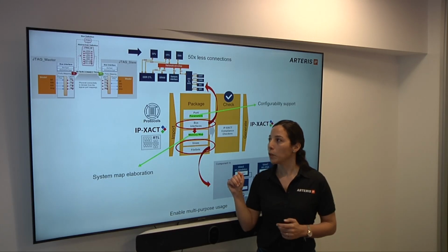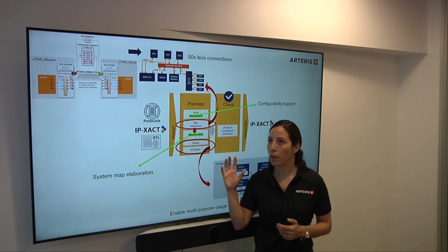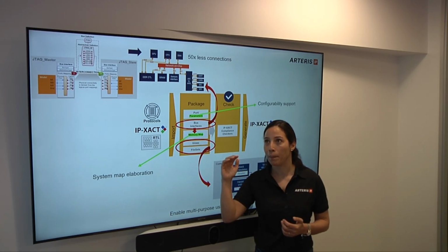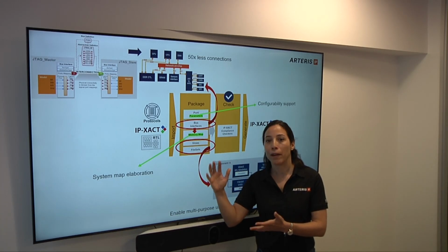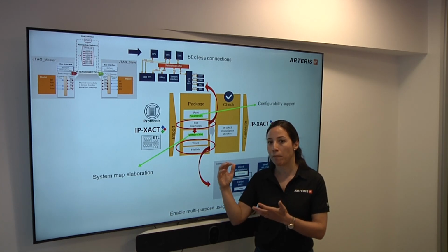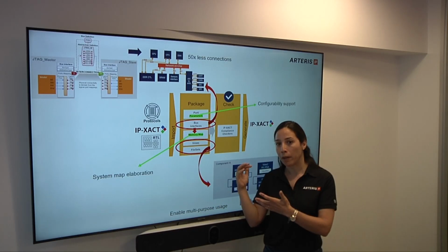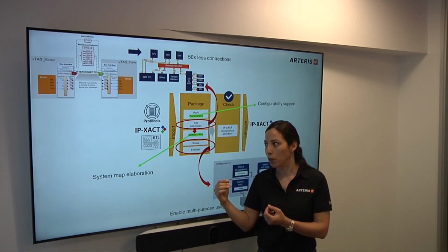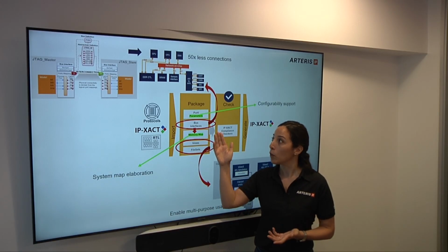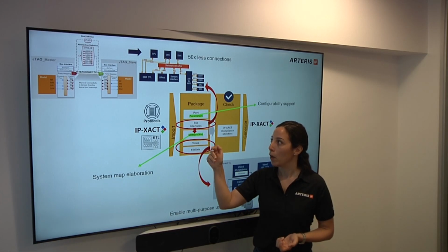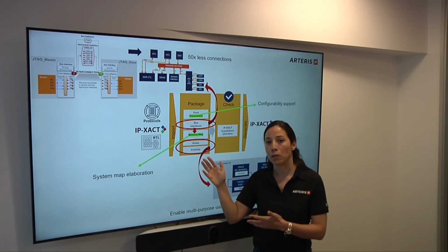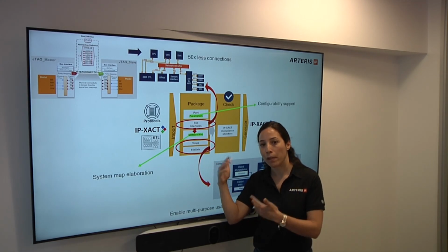Yes, actually, the benefit of packaging the IP is that the more information you put in this packaging, the more benefits you will have at the end, because this information has been validated, so the integration will be reliable, and at the end you will have a better integration and better quality of your design. So on top of these elements that I described earlier, with the parameters and the bus interface, we also have the description of the memory map. This will help to generate all the collateral needed, like a VC header and UVM-RAL that will be used for the